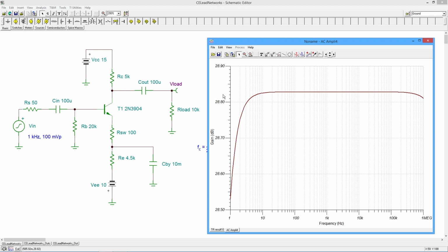this scale is only in tenths of a dB. So that's not even really audible. That's a very, very small percentage in terms of a gain change. In fact, 3 decibels, and this is a key thing to remember, 3 decibels represents a doubling or a halving of power. If a signal goes up by 3 decibels, the power associated with it has doubled. If it goes down by 3 decibels, the power has been cut in half.